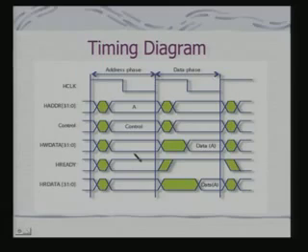Depending on the status of the HREADY signal, there will be wait states introduced. So in this case, your data which is here is delayed. I introduce a wait state over here. Similarly, for the read also there will be the data phase which will get delayed.